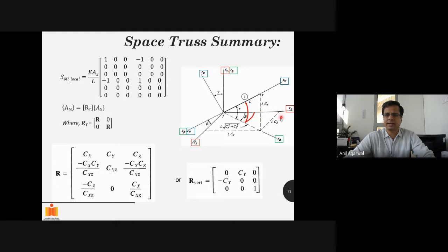We rotated the global coordinate system about the global y-axis, as shown here, by an angle beta, in such a way that my x beta, or xs after rotation by beta, is right under xm, vertically below xm. Then we rotate the global coordinate system again with respect to z beta, by an angle gamma, until my x is aligned with xm.